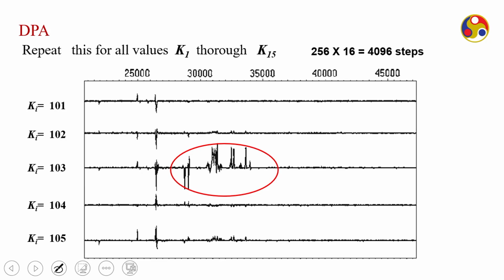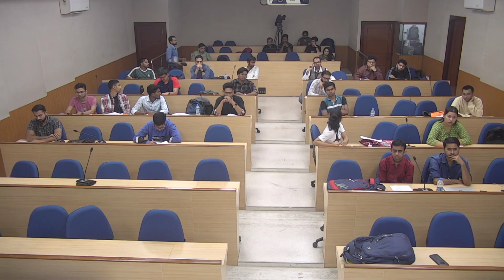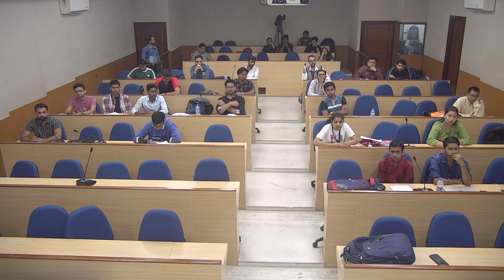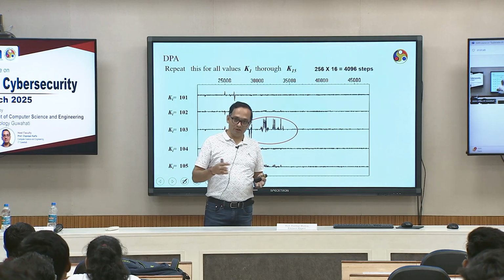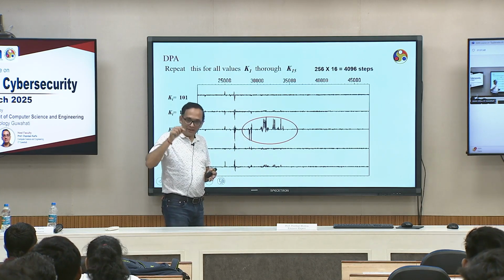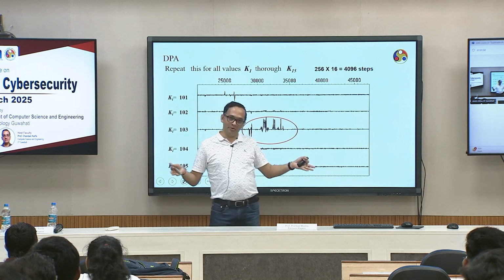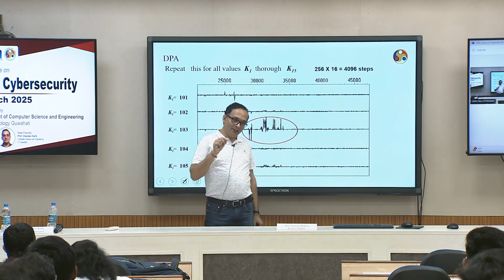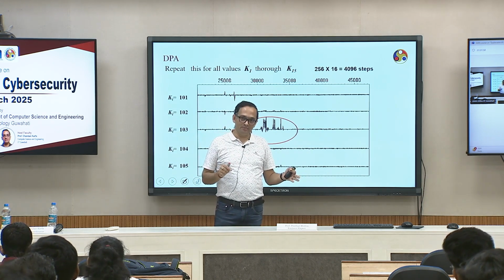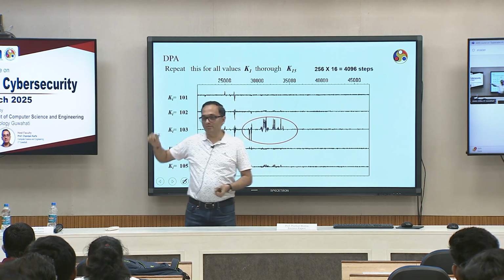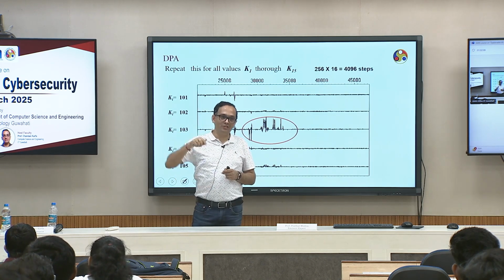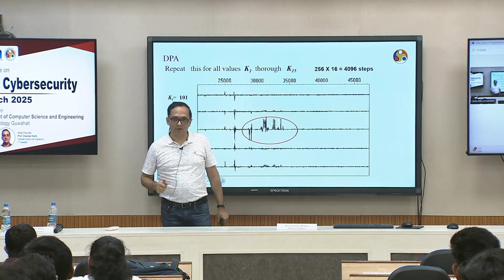Sir, how can we say that by making the LSB equal to 0 or 1, we can test the keys? Yeah, it's a good question. Your LSB may not be able to distinguish, so then you have to take the next bit and so on. Effectively, you make the LSB equal to 0 and the other bits arbitrary, you run for 10,000 cases and plot the power pattern, and then you make it 1 and the rest of the bits again random, and plot the power pattern again. If they are distinguishable, that means this bit is actually having an impact on the overall power.